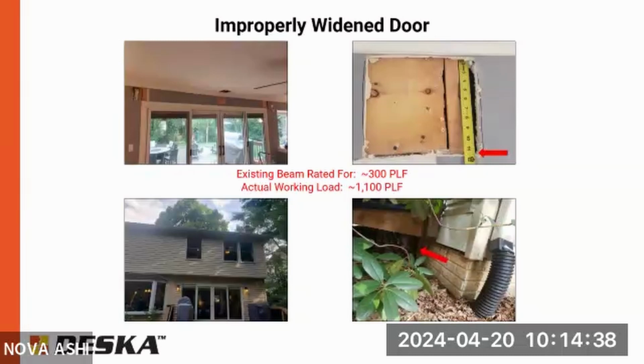In this case, the window was under a deck. The owner didn't care. The easiest thing to do was to install some rebar, terminate the window well, and fill it in with grout, concrete.